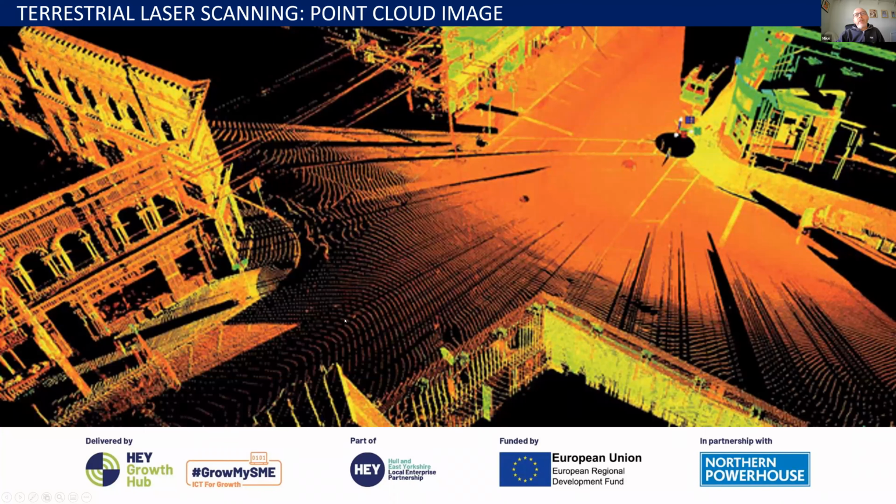And as the scanner fans out, you can see that these points become more dispersed. We can control the density of those points dependent on the distance of the object and the quality that we want. But obviously, the more points you lay down, the more memory it eats into. We do generate large data sets when scanning buildings, usually from several gigabytes to many gigabytes in low terabytes. So it's very intensive in terms of file size. But here you get an idea of how the scanner disperses those points to create points in space.